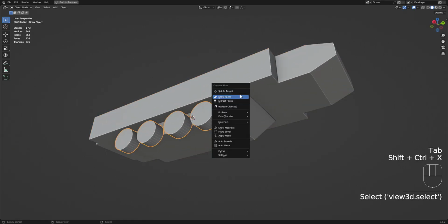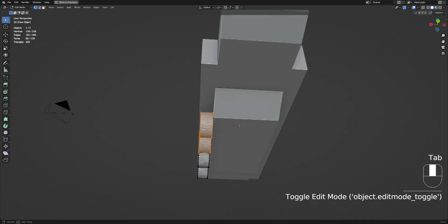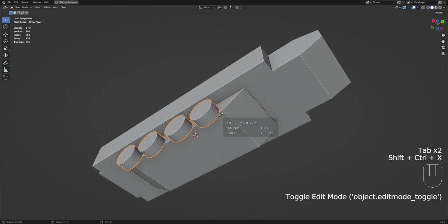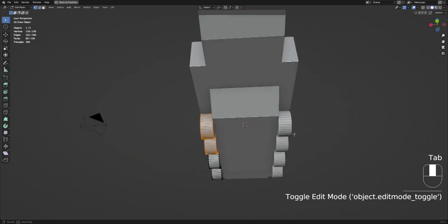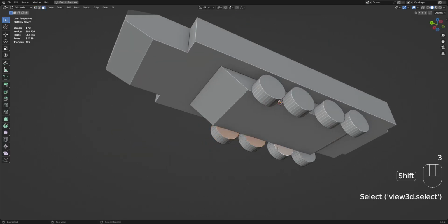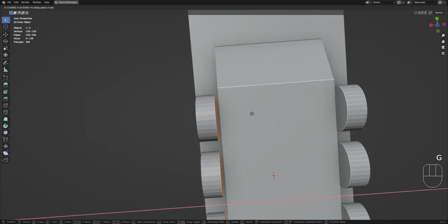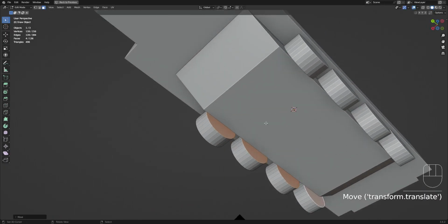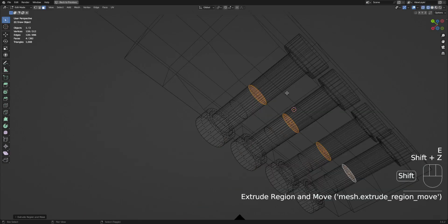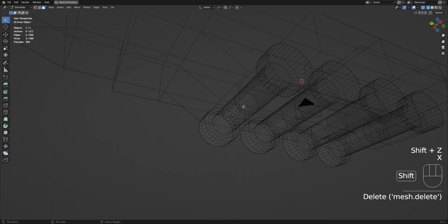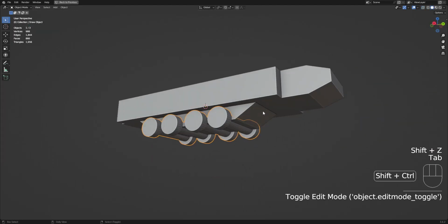Okay, applying this so they become real mesh, and then establishing the bevel in the x-axis and selecting these faces here. Bring them back like that and inset and then extrude in the middle and X F to delete the faces in the middle.